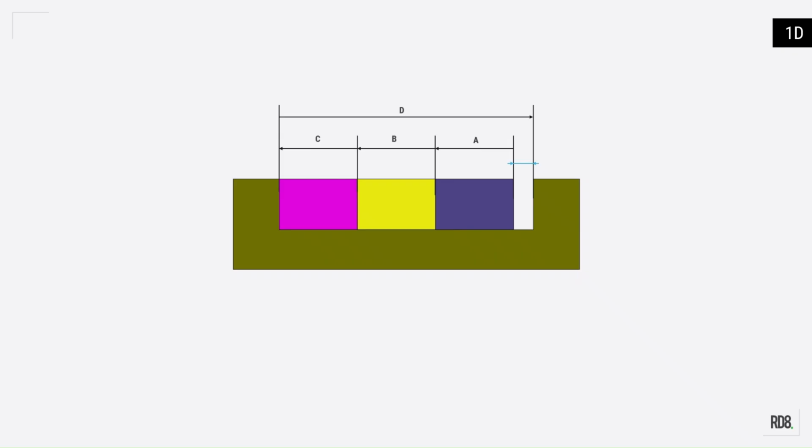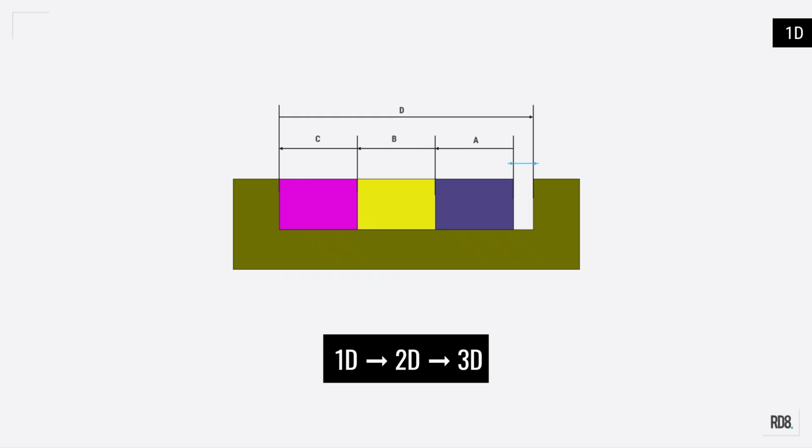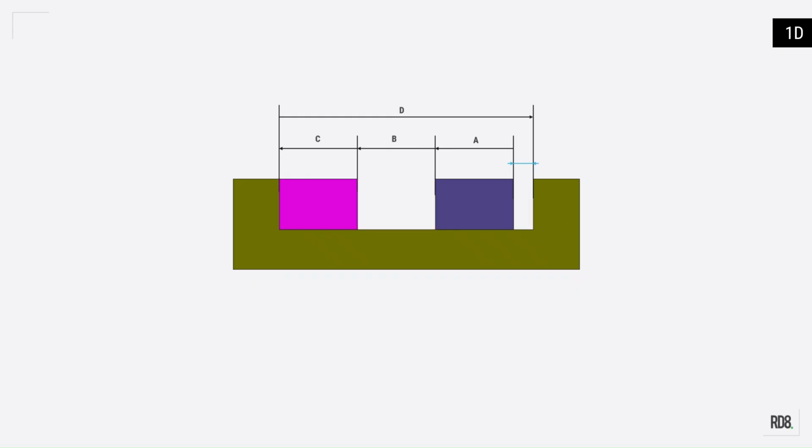need for 2D stacks. This is a 1D stack. We'll use this case to explain the differences between 1D, 2D, and 3D stacks. We might want to change one of the boxes to a cylinder, and in the shown example, it does not really change our tolerance stack. The cylinder's width is given by its diameter, instead of a length between 2 opposing planes.